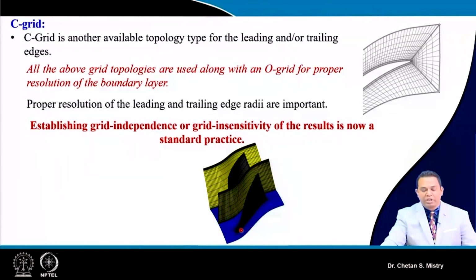Here if you look carefully, this is representing the blades, and here you can see we have systematic grading near our hub surface. In the same way, this is representing what is happening along the span. We can say this is a passage block, and near the tip region is our interest. In order to capture the tip leakage flow, we are looking for such kind of elements. And this is representing the periodic surface.